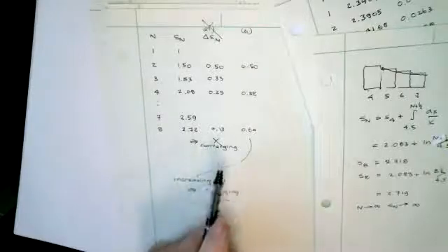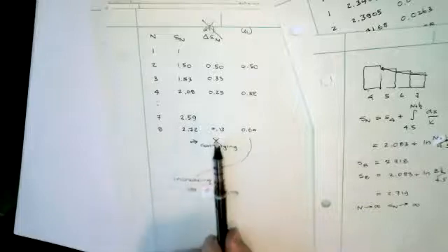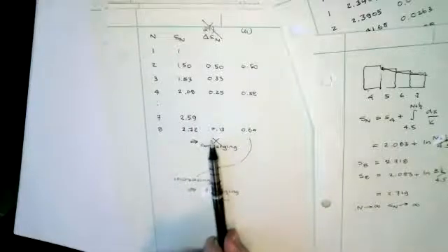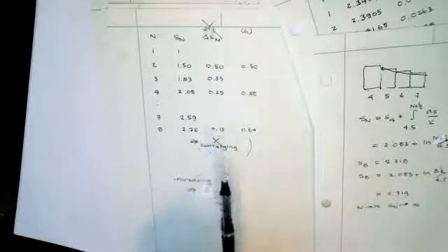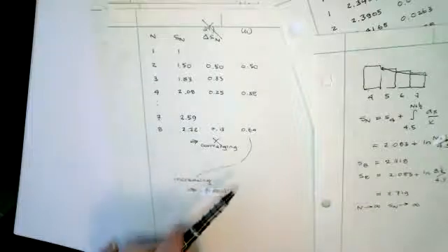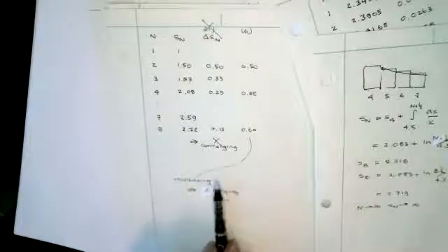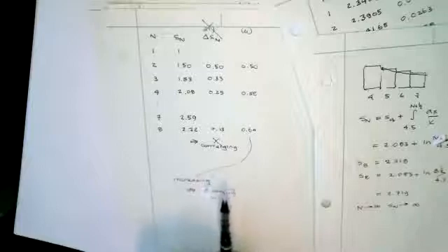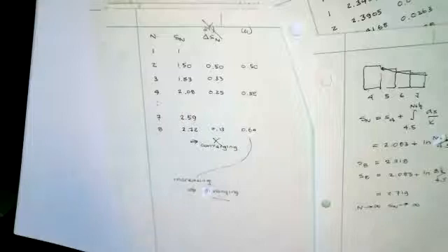Whereas if you just do n to n, the reason people did this is because they started with a big mesh. And then they quickly realize, well, I don't want to go to 100,000, 200,000. Pretty soon I'm going to be up to 1 million. That's about my limit of my capability. That's no longer true. Probably you can run 10 million elements now. But even so, you get to 10 million far more slowly when you start with a few hundred thousand and just keep going up. The reason for doing it was because it's easy to do without thinking about it. Well, it doesn't work. It gives you the wrong information.